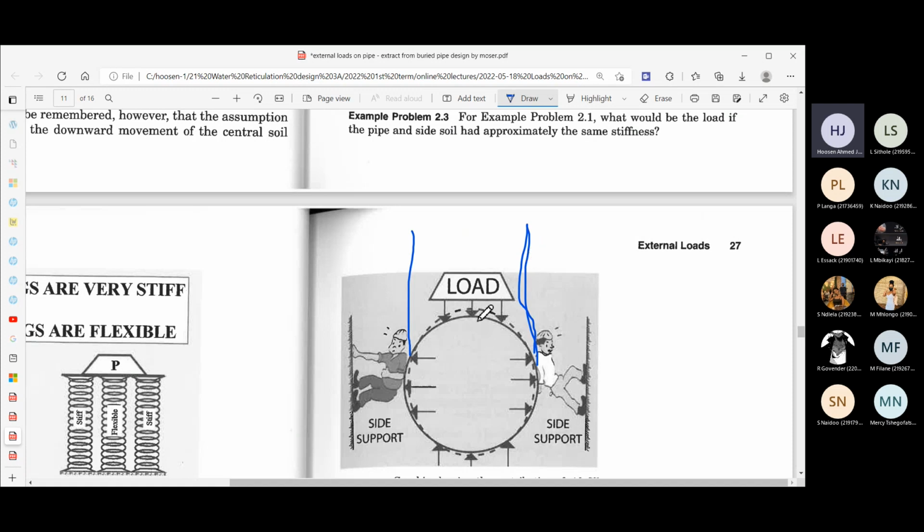But this pipe is, by its definition, rigid. So it stands its ground and it doesn't give anyway. So it's not deforming like what we see in this particular diagram. So a rigid pipe, by definition, right, what's the difference between a rigid pipe and a flexible pipe? A flexible pipe can undergo a deflection of 2% or more without any duress. Right. So without suffering any detrimental condition, or without its strength being weakened, or without it being cracked in any way or whatever.